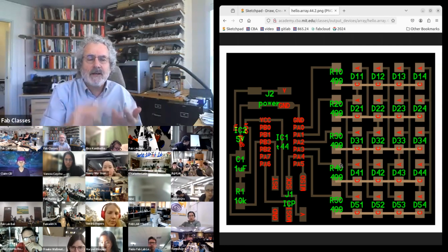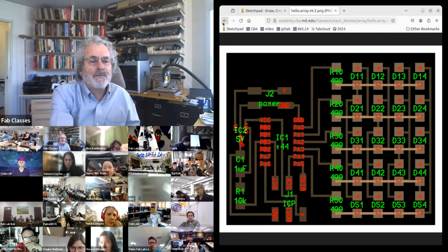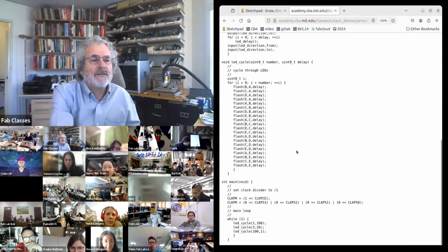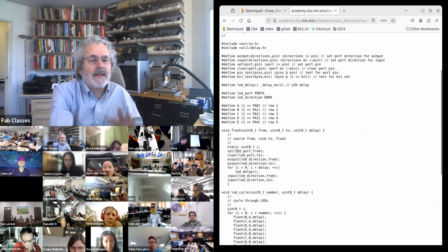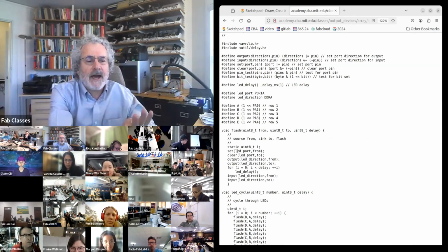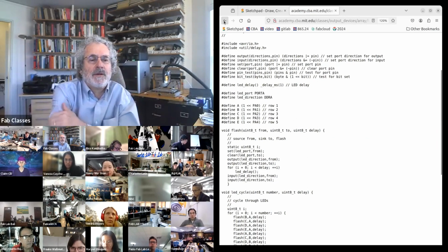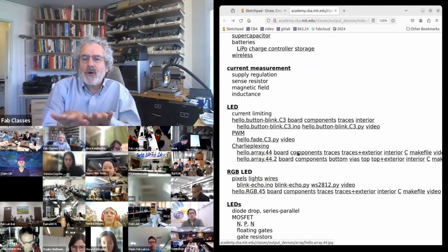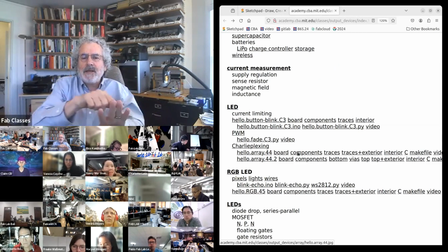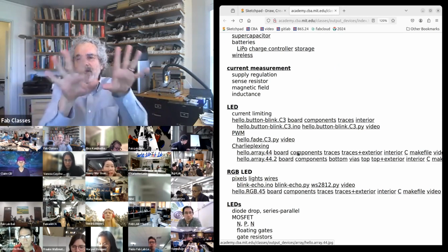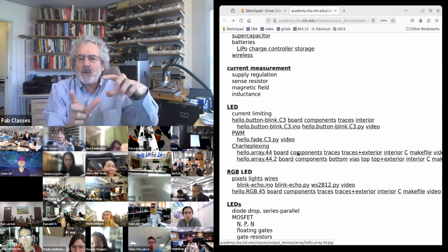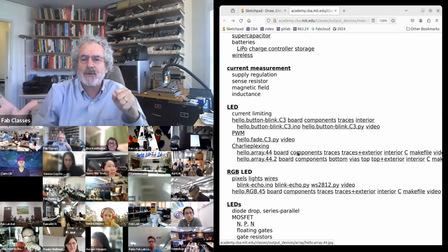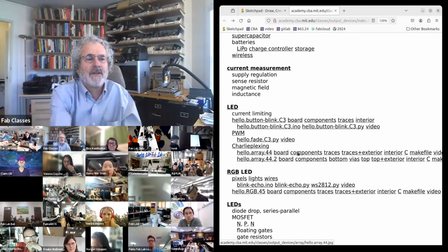And if I look at the code to do it, I'm taking turns setting pins to be inputs versus outputs. And I'm switching which pin is an input and which is an output. So Charlieplexing lets you control many more LEDs. And these could be in a straight line. They could be a bar graph. They don't have to be in a square array, but it lets you control roughly N squared LEDs with just N pins. So that's Charlieplexing.